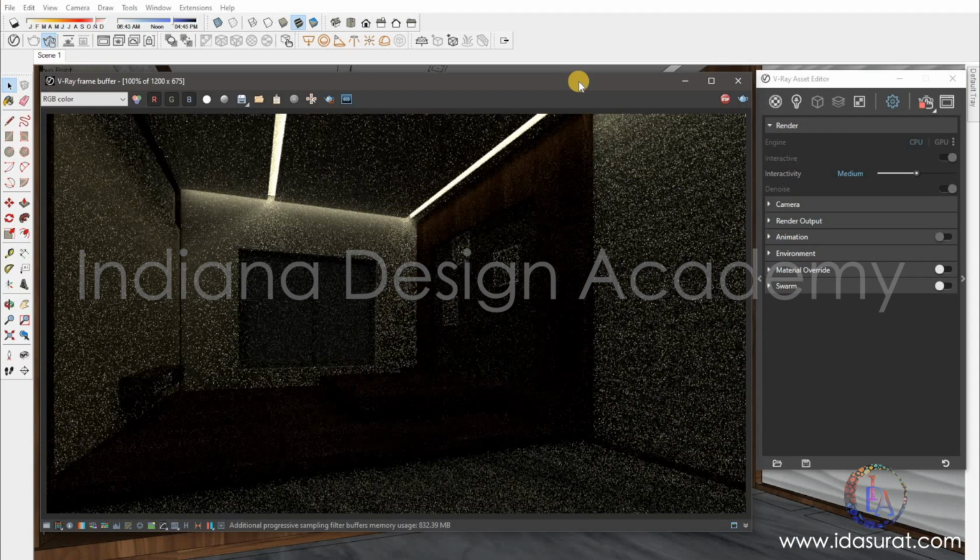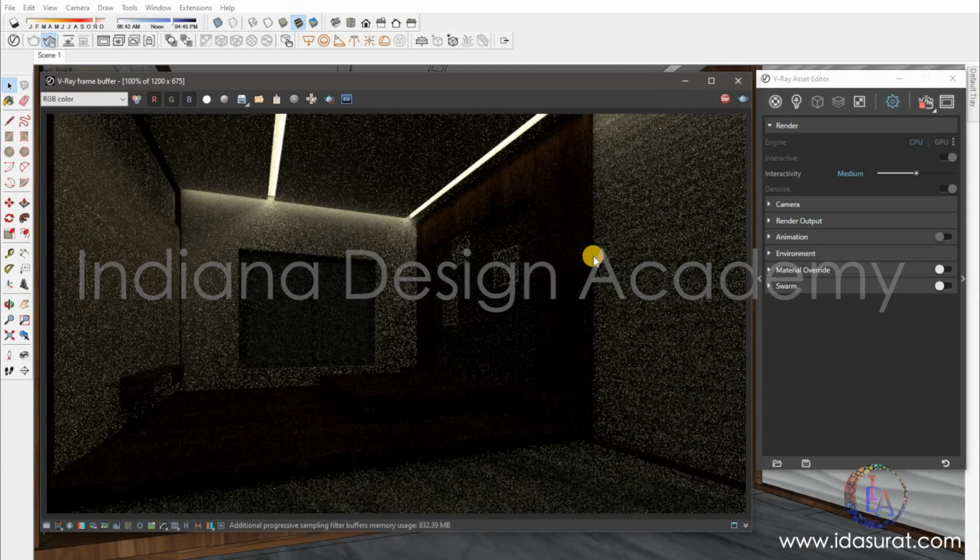It is necessary for me to place both the lights separately so that if I want a different adjustment, I can adjust it. Otherwise, if I copy the same one and change one, it will change in all. So it is better to keep the lights different. If you want a different intensity, always make a copy and then set it. Now I will stop the render. I see a bit of dullness over there, and this one is quite brighter.